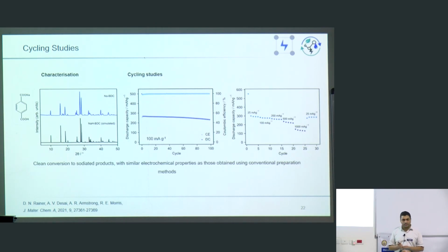Right, so with ball milling, is it the friction that actually? It is the friction and the local heating that is caused by the friction. That's actually a good point, because there is no quantification of the amount of heat that is produced during the synthesis, but there are thermal maps which show that some heat is evolved because of the friction. But that will generate abnormal shape and size of particles. Yes, yes. That is the thing that you optimize. You have to work around the frequencies of the milling, the sizes of the balls, and of course the particle sizes you start with. If you know all of that, you can work around it and end up getting particles that are very uniform in nature.